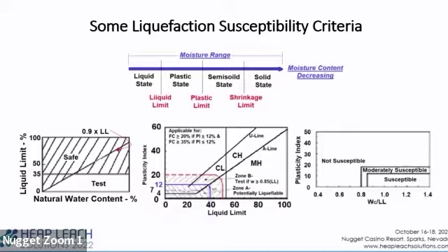There's kind of a next level. You can go get a little more sophisticated, but I think in general, you look at plasticity index and liquid limit a lot as kind of right out of the gate. It's a cheap test. Every soil mechanics lab in the world can do it. Every first year soil engineer can do it. So it's a cool tool.